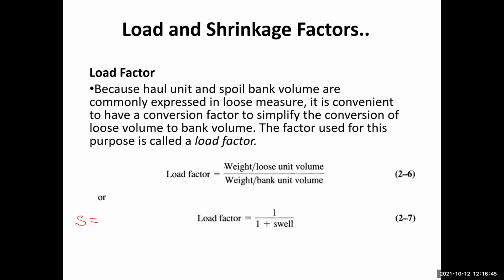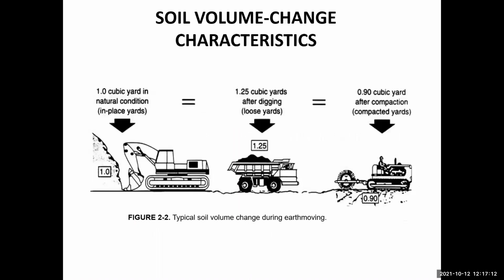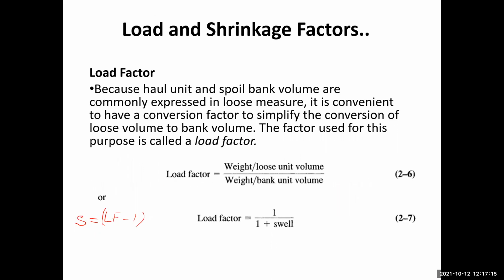So the load factor: weight per bank volume, weight per loose volume. So the swell formula is basically the load factor minus 1, right? The swell formula is the load factor minus 1 multiplied by 100. So that is the load factor. So for example, over here, what is this load factor? Weight per loose volume divided by weight per bank unit volume, okay? So this is the load factor.